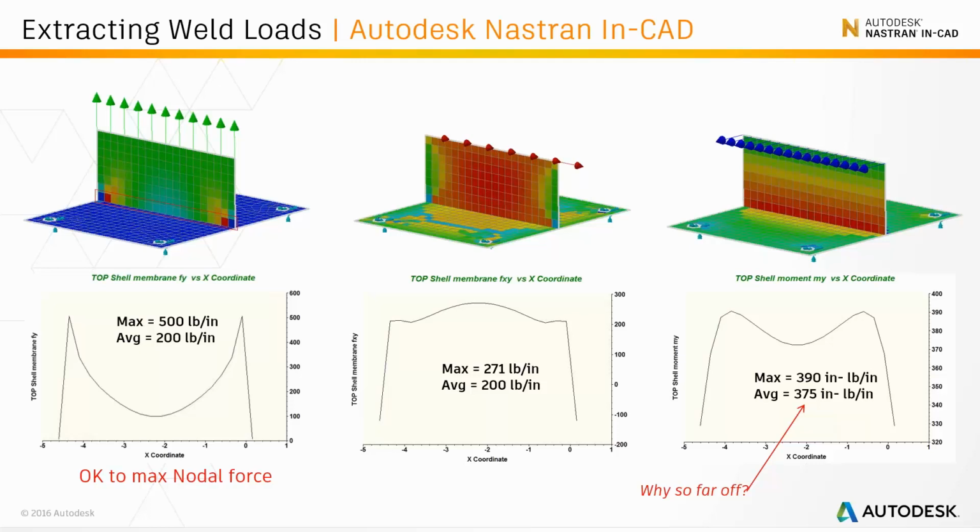Well, the easiest way to do that would be to add mesh refinement along the edge of that shell element, and then reduce the mesh size down to a significantly small value so that the bending moment in this case is accurately represented.